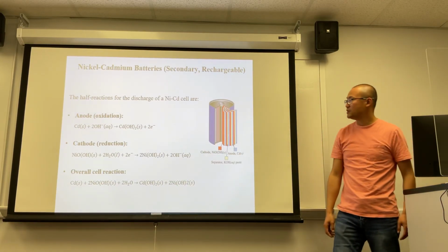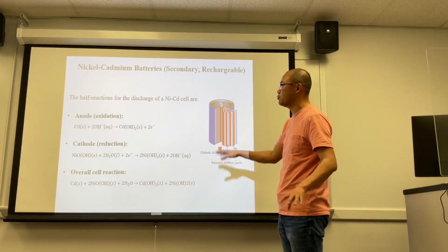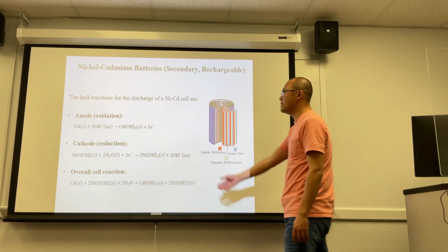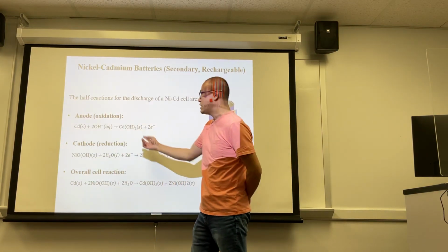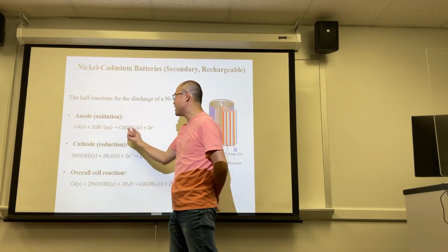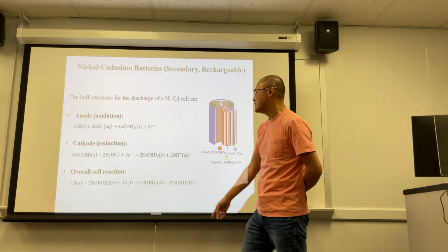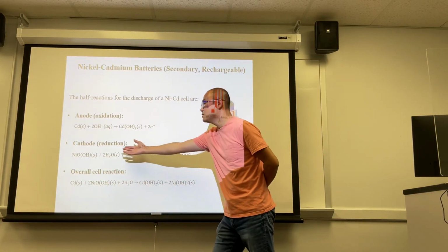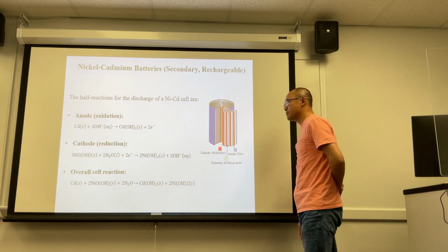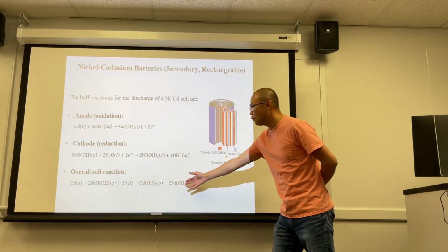Okay, next, let's take a look at the nickel cadmium cell again, but now we're not showing the simplified reaction, because this is what's really happening inside the nickel cadmium battery. Okay, cadmium again is the anode, losing electrons, and after losing electrons, cadmium combines with 2 hydroxide to become cadmium hydroxide. Okay, this is what happens in the anode. The cathode is nickel oxide hydroxide. Again, it gains 2 electrons to become nickel hydroxide, and you add the two reactions together, you get the overall reaction.